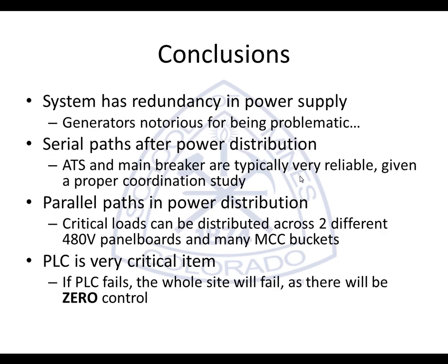So some conclusions to take away. The system has redundancy in power supply. It's got both the utility feed and the generator feed. However, generators, as seen here, are notorious for being problematic and not starting up and distributing power when you need them.